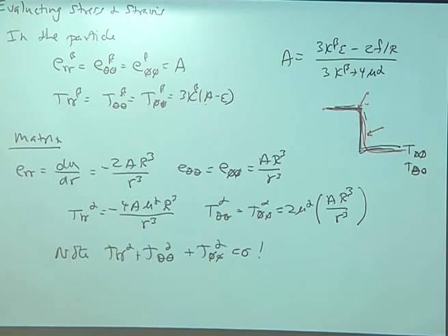If you go into the particle, the shear modulus equals 0, so you only have the bulk modulus divided by F, which gives you the stress. So you go back to the fluid case, but the fluid in this case has 0 pressure because the shear modulus is 0. So it all fits together. If you have a fluid model, you have no shear stress, no elastic energy, and basically nothing going on in the matrix.